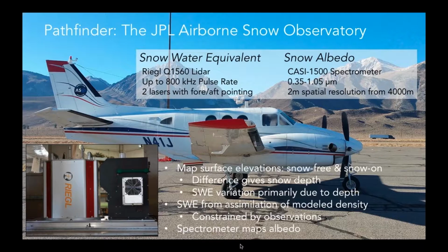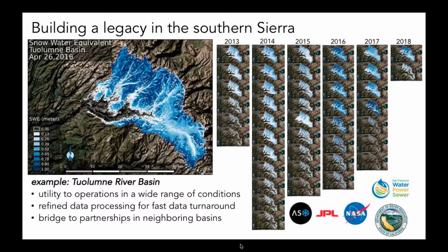And just one example here from the city of San Francisco's Hetch Hetchy operation. This reservoir provides water and power to the city of San Francisco and a bunch of users on the peninsula. They have one source of input to the reservoir, that's snowmelt. It barely rains at all in the summer there. And then they have at least 3 competing management goals: in-stream flows for ecology and other downstream users, power generation, which if they fail to meet, they have to buy power on the open market, which is very expensive, and then water supply, of course, obvious ramifications if they miss that. So better information on snowmelt and inflow to the reservoir can produce much better outcomes and optimize their management.